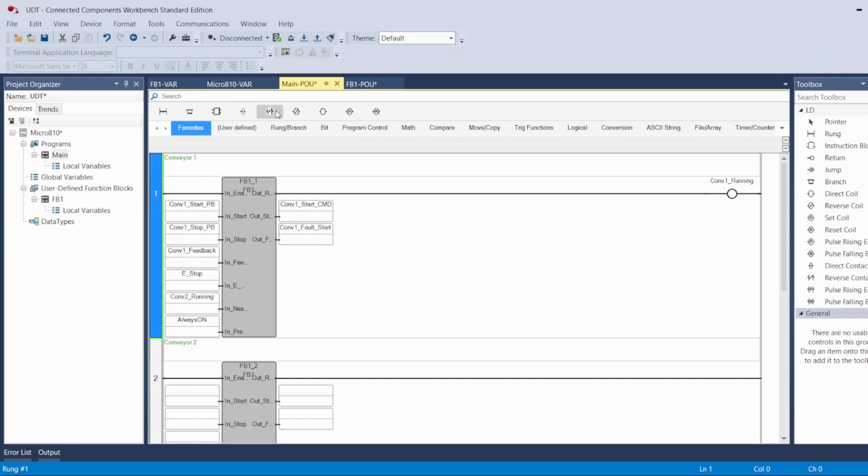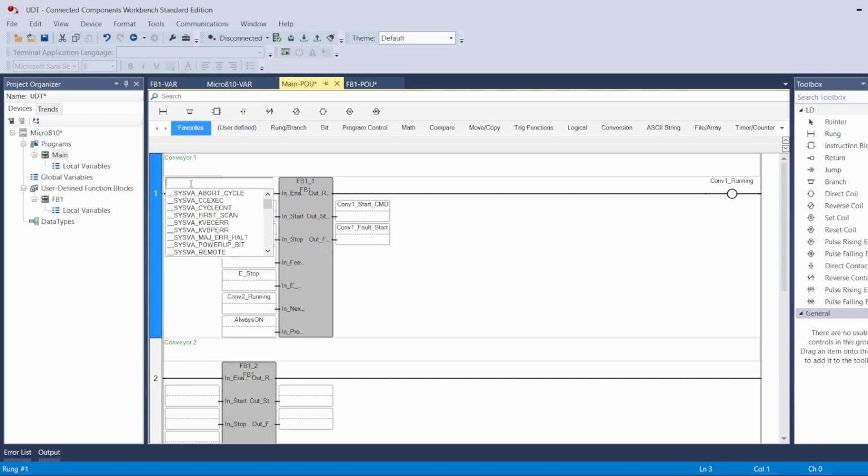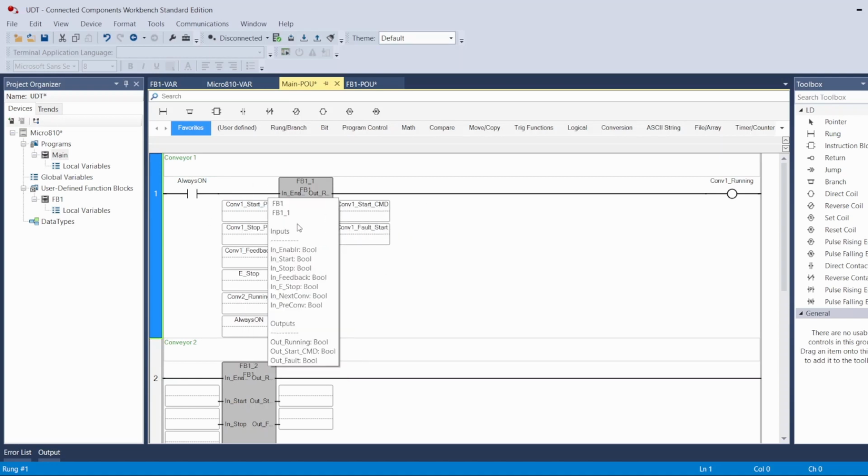You can add a tag right here where I'm gonna use, for example, the always on tag, but you can use a special tag or whatever where you can disable this block so that signal will never go there. So whatever buttons change, whatever happens here, it doesn't affect your outputs at all anymore. So you disable it. It's gonna be like a live bit to activate and deactivate this block.